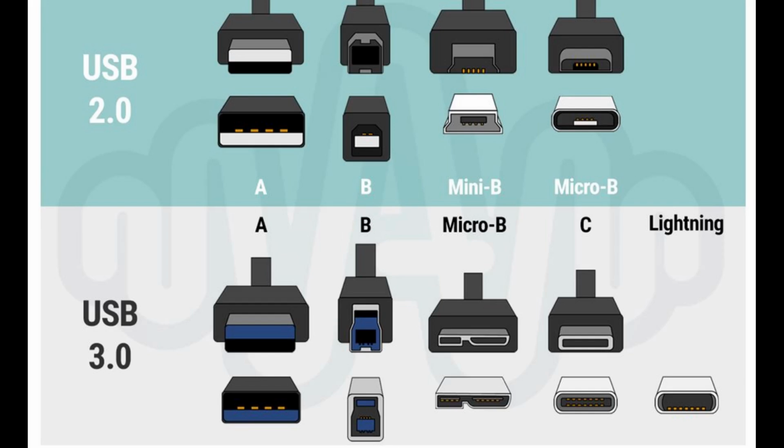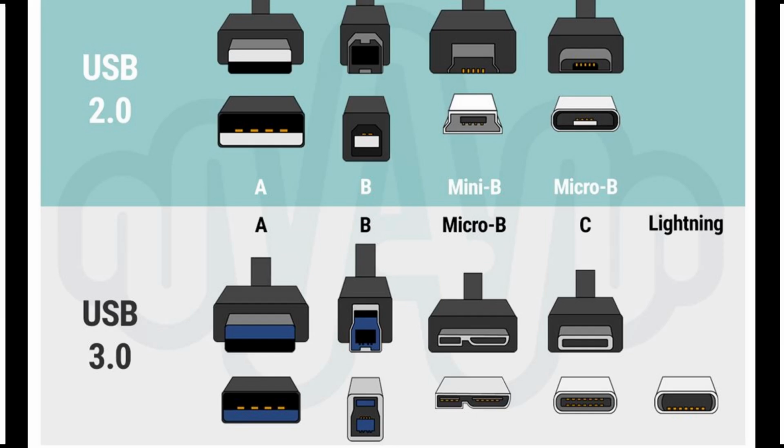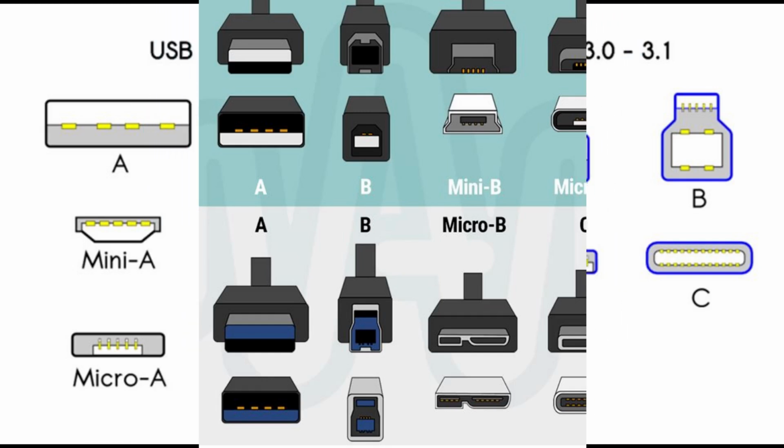There was no known miniature Type A connector until USB 2.0, revision 1.01, introduced one. USB 2.0 was released in April 2000, adding a higher maximum signaling rate of 480 Mbit/s, maximum theoretical data throughput 53 MB/s, named high speed or high bandwidth, in addition to the USB 1.x full speed signaling rate of 12 Mbit/s, maximum theoretical data throughput 1.2 MB/s.